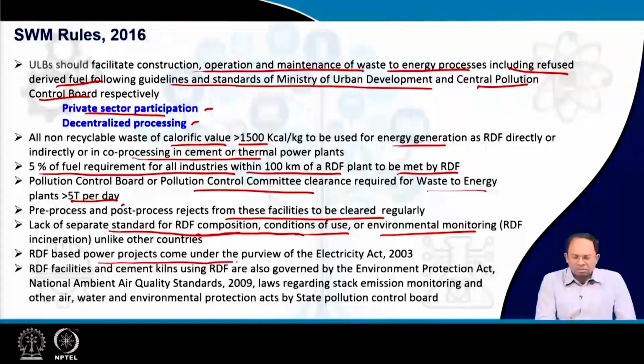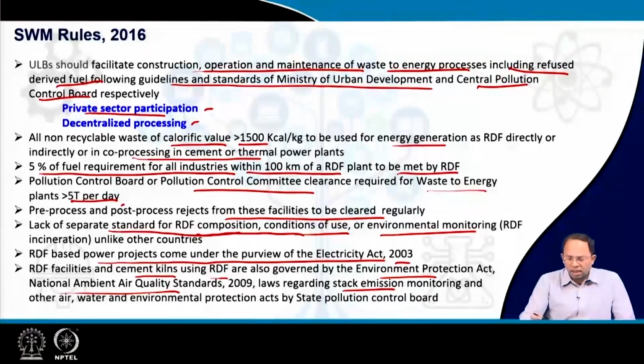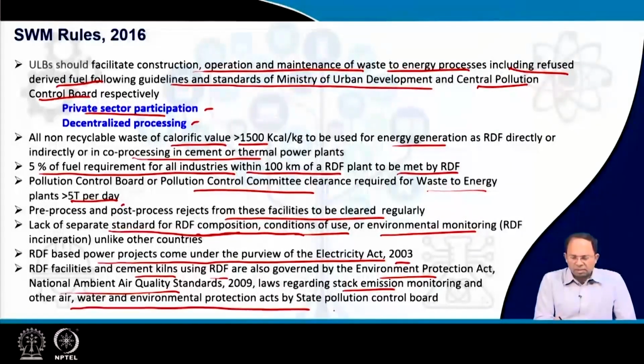RDF based power projects come under the purview of the Electricity Act 2003. RDF facilities and cement kilns using RDF are also governed by the Environmental Protection Act, National Ambient Air Quality Standards, and laws regarding stack emission, meaning what kind of smoke or emission they release, and other air, water and environmental protection acts by the State Pollution Control Board. So adherence to all these different standards and laws has to be there when you set up waste to energy plants.